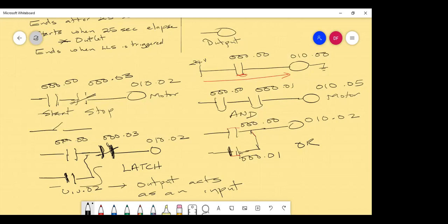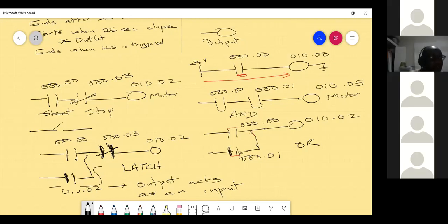But here's the problem that you have. 2 years down the line, the switch stops working, or somebody decides, well, we need to change out the switch, and then buy a push button switch. So you have the program like this for the start and the stop. This only works with a single throw, single pole switch. This construct works no matter what.